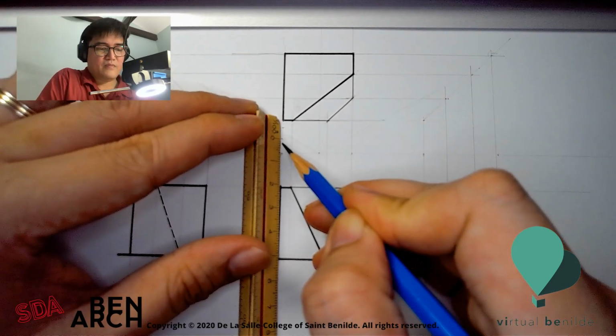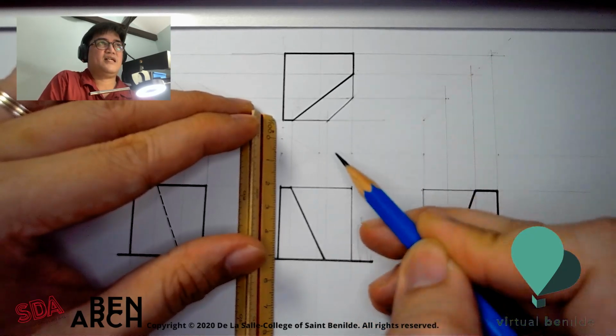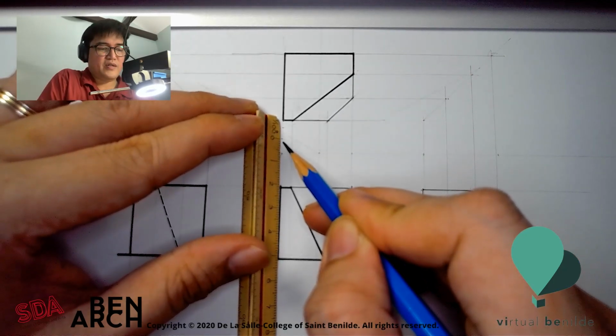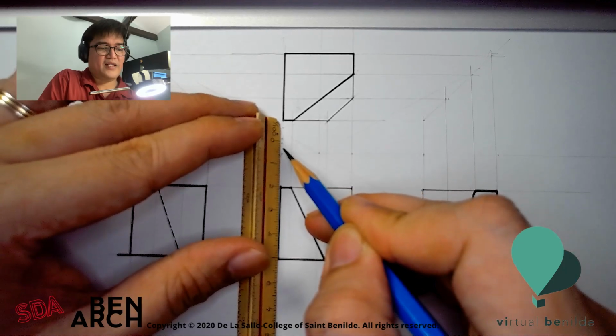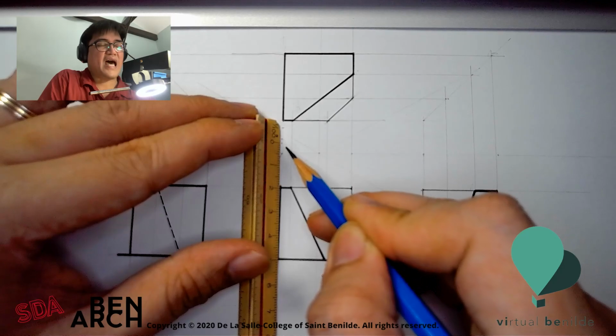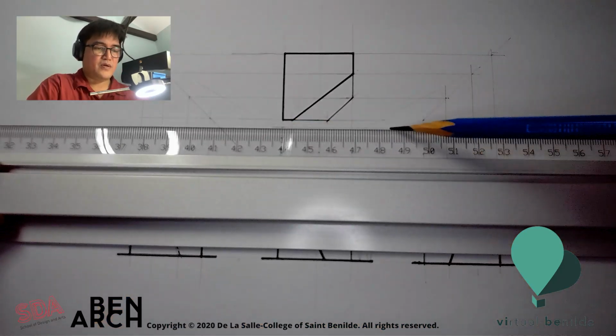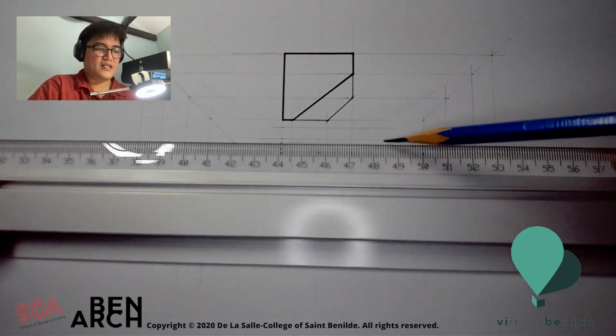Here, I'm going to put in the label scale, or what scale this is going to be. So I'm going to use a 3 millimeter height text, 1.5 millimeters gap, and then followed by a 3 millimeter. I'm going to do some extended guidelines.